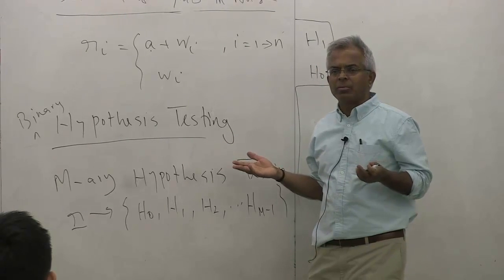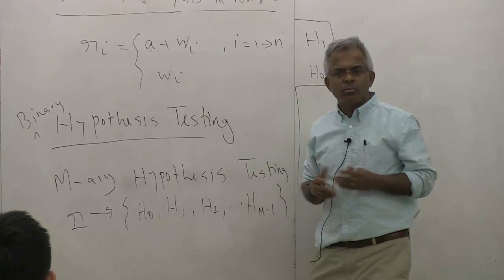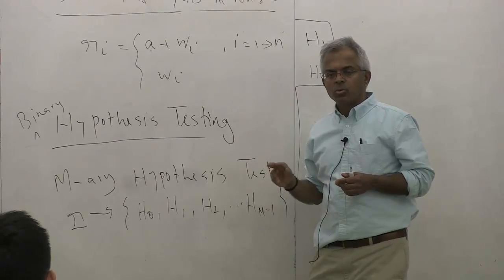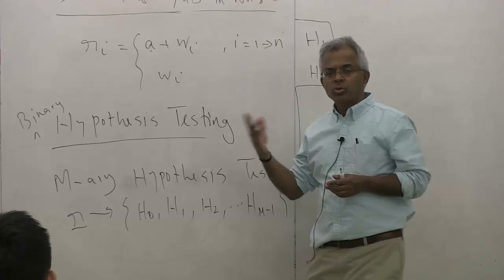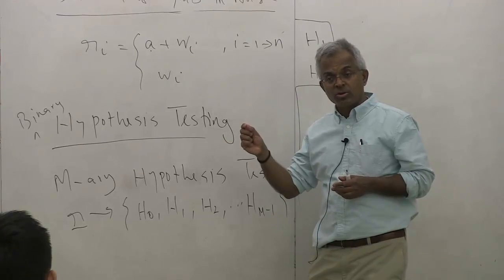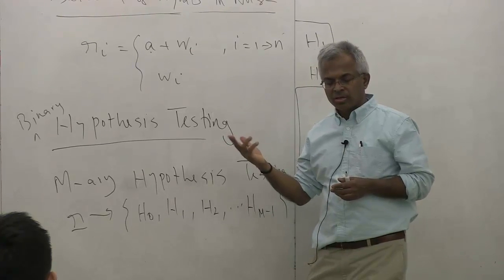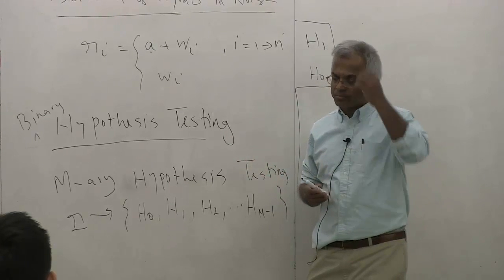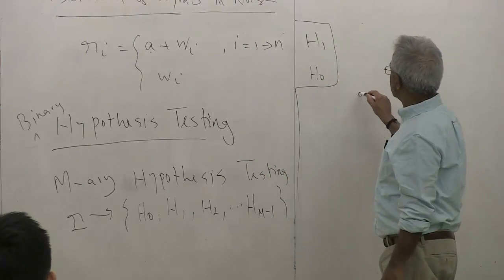So where is this applicable? Even in communication, you have of course heard about BPSK, where it's one bit at a time, or if you take bunches of 2, that's QPSK, right? Because 0,0 is one hypothesis, 1,0 is another hypothesis, 0,1 is hypothesis 2 or 3, and 1,1 is hypothesis 4.